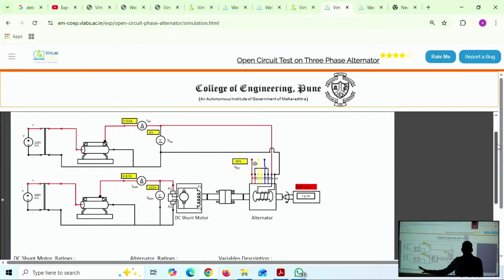They manufacture. I think in India we have BHEL, Bharat Heavy Electrical Limited, the company that manufactures these equipment. Every equipment they manufacture, they cannot load it in the field and then test and pass the certificate, saying we calibrated by actually loading. No, they test it. How do they test? Short circuit test. These are the tests, by providing small voltage and by varying the excitation. That's it. After taking care of that,